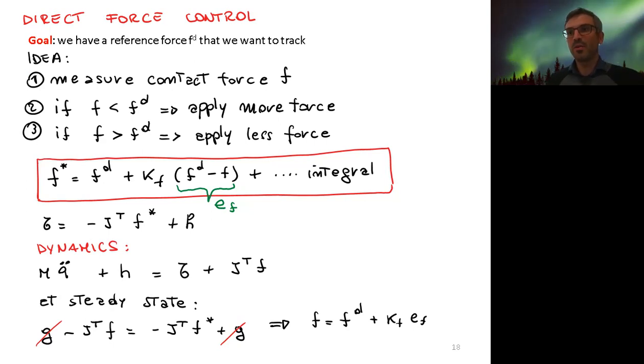Passive methods involve introducing passive elements in the kinematic chain, and passive means springs or dampers that do not produce any energy internally, but can be used like RCC devices to accommodate the interaction forces that can emerge if you have interaction with the environment and your geometric trajectory is, for example, entering the environment.